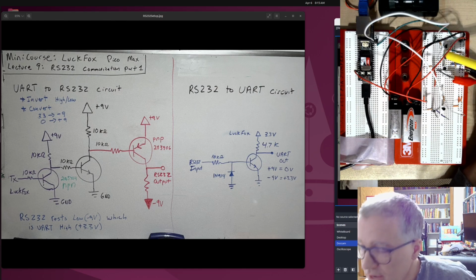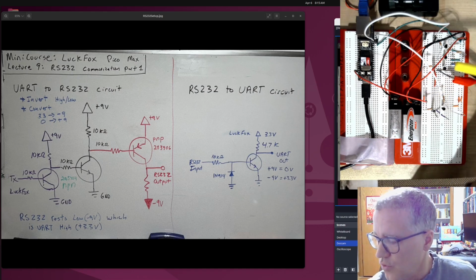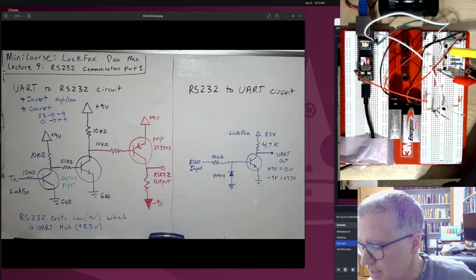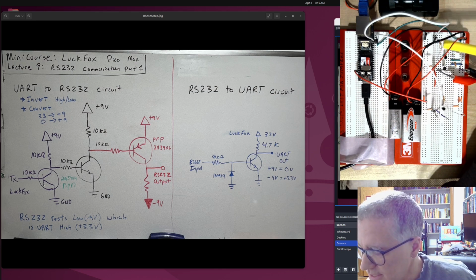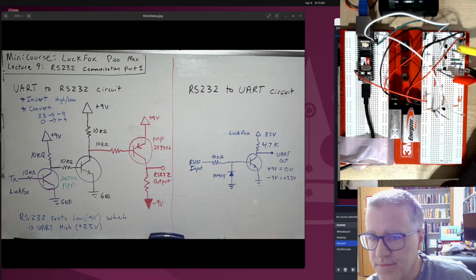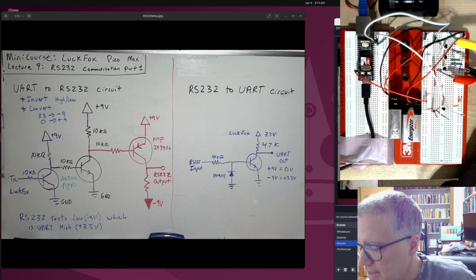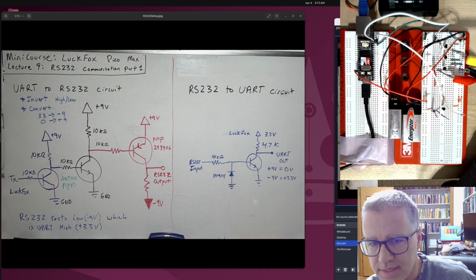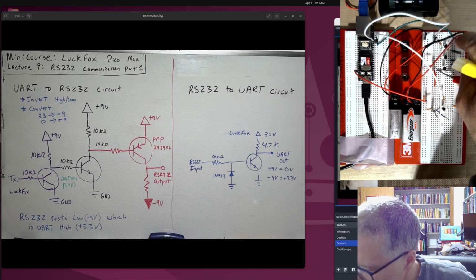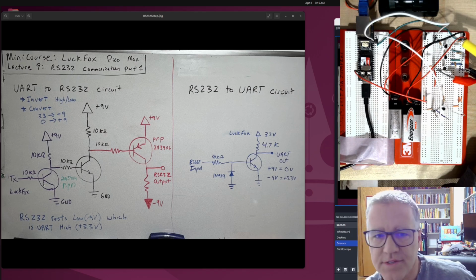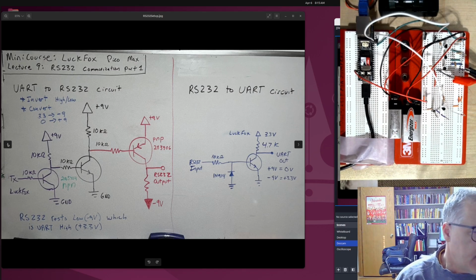Now, this transistor and the other 3904, the flat side is facing towards the pen. So as we look from bottom to top, it'd be emitter, base, collector. So here we're in the base. The emitter part is grounded directly, so that is going from the emitter line. This green is taking us from the emitter to the ground, and then the collector has a 10K, that's this one right here, that is taking us up to the positive rail. So this 10K takes us to the +9, and then we're just grounded directly on that emitter.